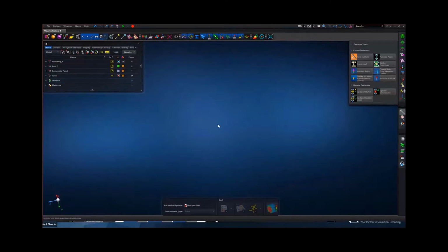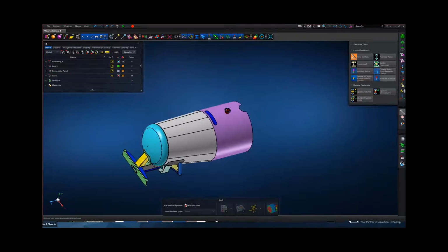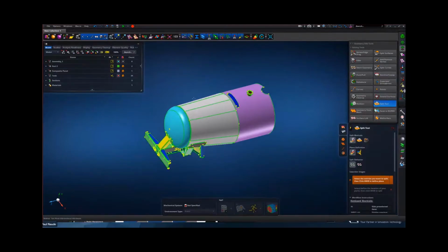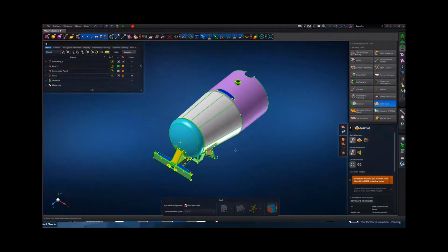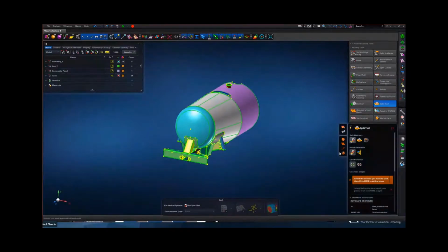Right, another tool that is quite handy to understand about the user interface is that everything on top here is purely manipulating visualization. There are no physical tools that have any special functionality other than the ability to hide surfaces, solids, etc. So for instance, in this case, we can now quickly only hide that, only show our tank. And what I want to do with the tank is work with a quarter model. That speeds up the whole cleanup process, obviously, because the full complete model is symmetrical in two directions. So if we split this, let me just split it in that fashion.